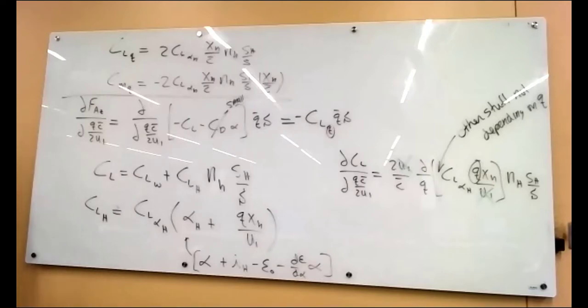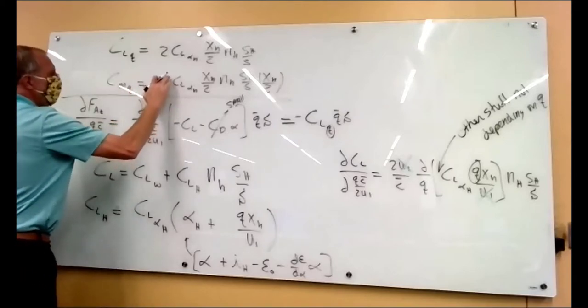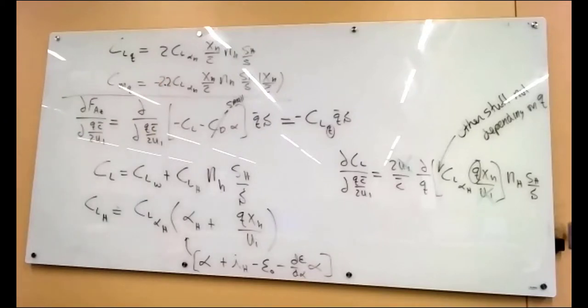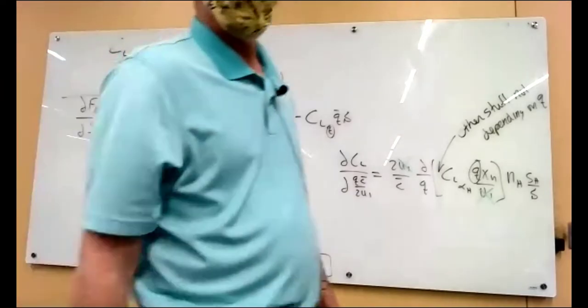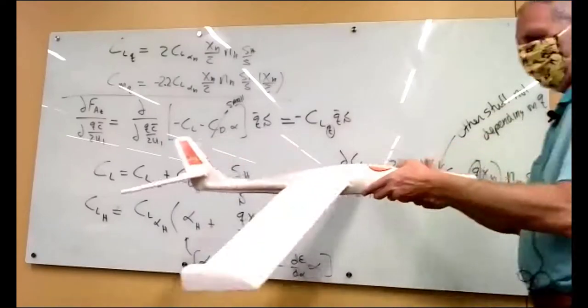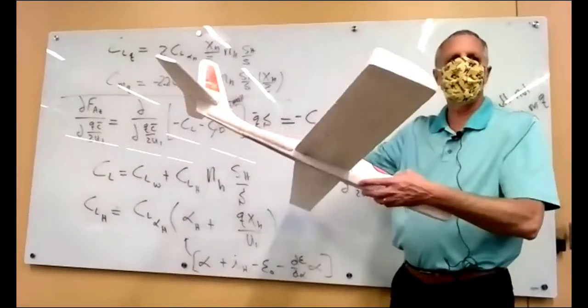So if you look this formula up in the book, instead of a 2 here, it has a 2.2. So you look at that and you go, where'd the 0.2 come from? Well, it turns out that from experience in wind tunnel tests, when the airplane is pitching, center of gravity is like right here, you get a little bit of wing effect because it's rotating as well.